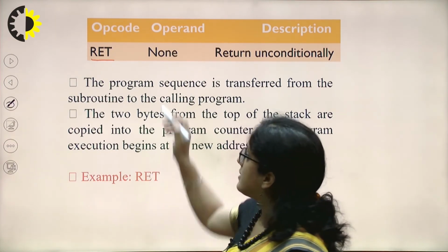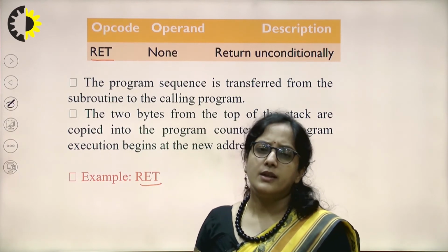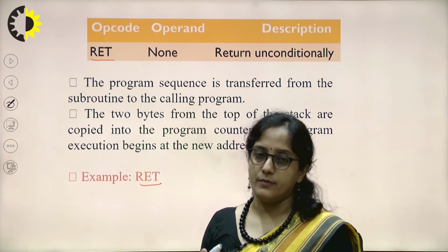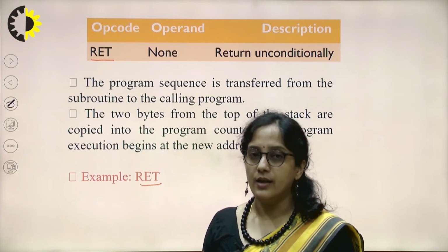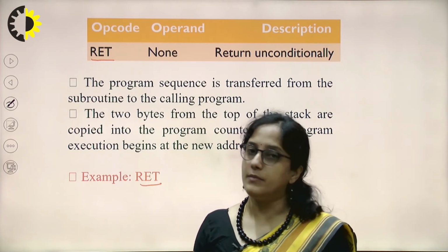Whenever this RET instruction is executed, the program counter is popped, meaning it will be reloaded with the previous location in the main program.